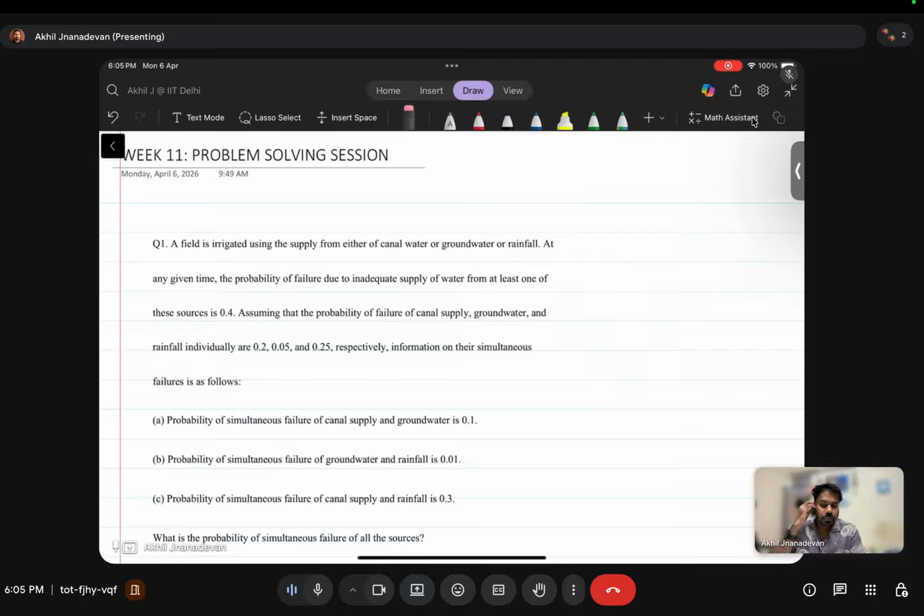For example, when we are dealing with a precipitation variable, there can be uncertainty due to the measurement. There can be measurement errors, instrument errors, and also manual reading errors. So these are a type of uncertainty. And if we are trying to model the runoff using this rainfall, which has some uncertainty, the runoff that we are getting will have the uncertainty propagated from the uncertainty that was already there in the rainfall. And also, there will be model uncertainties.